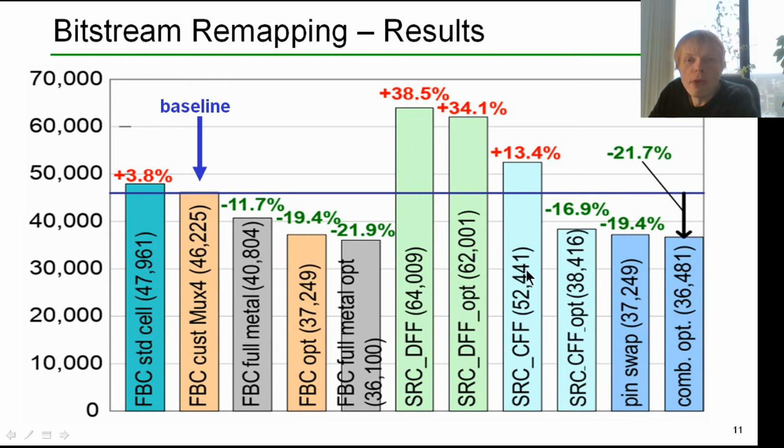There is another open source FPGA project called Open FPGA, and they try to mitigate the huge cost of D flip-flops by providing custom flip-flop cells, which are not really smaller than latches as we use in FABulous. But we played the optimization game for an assumed architecture that would use those custom cells, and even with those optimizations, it is still worse than what you could get from frame-based configuration.